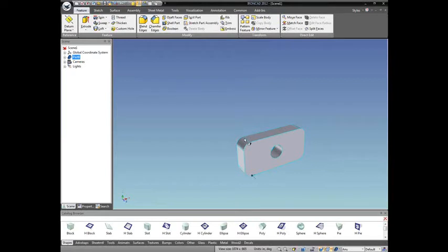So I select the part now. One other thing I want to do is control the thickness of this plate, and that gets a little trickier because we don't have any profile dimension that will gauge the thickness, so we have to go to a size box dimension.